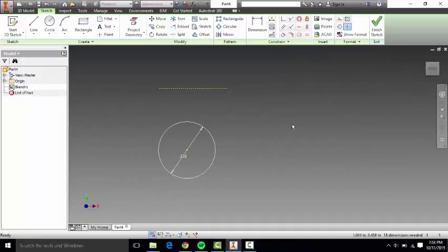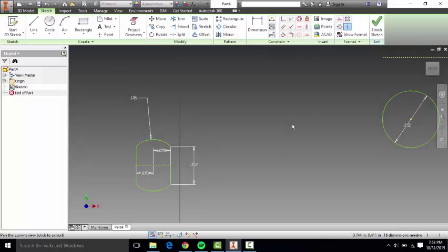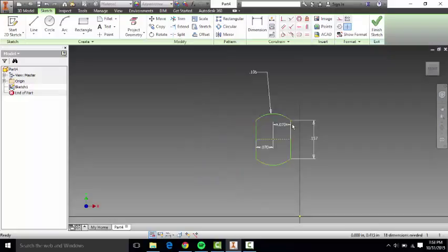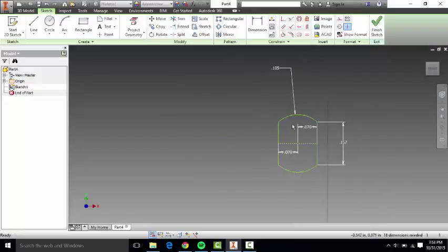Alright, now that we know about construction lines, we can create something a little more interesting. We can create the slot that all your DC motor shafts fit into. You can use this when designing gears, or wheels, or links, or anything you'd want your DC motor to be attached to. Let's start by creating a base circle of a radius equal to 0.105.